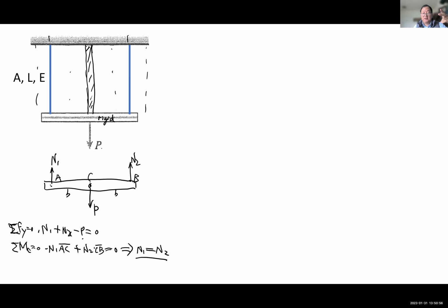Okay, for something a little bit easier as an example, since we have limited time, let's look at 3 cables here. Remember, now it's indeterminate. First we judge it's indeterminate, and it will be confirmed by equations later. So now we know we should use deformation compatibility.